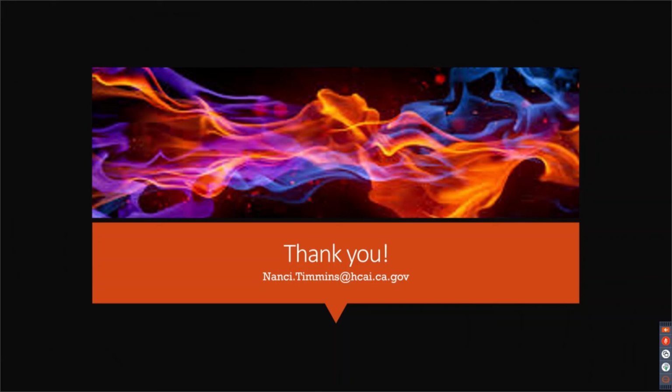You got 3 hour, it needs to be 3 hour, even if you got a 1 hour building on the other side that's crumbled and on the ground. Well, it's 5A, you get the 2 hour. But anyhow, if it's required to be 3 hours, it needs to be 3 hours. The table says 3 hours, that needs to be standing for 3 hours. So again, it's firefighters as well. We're protecting them too.